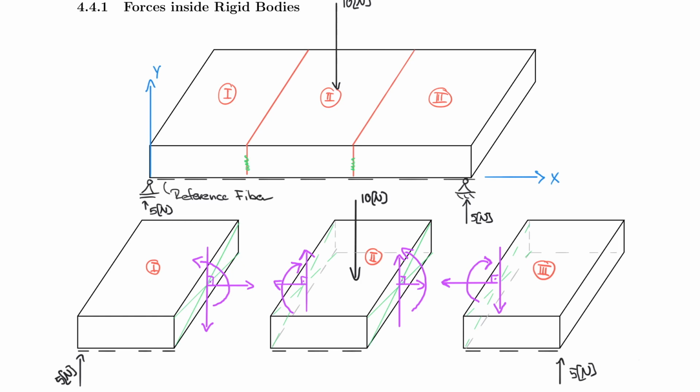So now you know that we have always on these surfaces 3 forces, the shear force, the normal force, and the moment, and that they always have to be in balance with the other side, with the opposite side. Otherwise, the system would not be in equilibrium, and if the system would not be in equilibrium, then the glue would not hold it statically together, right? So this glue line here makes sure that element 1 and element 2 are together in equilibrium. And that equilibrium is just shown symbolically here.